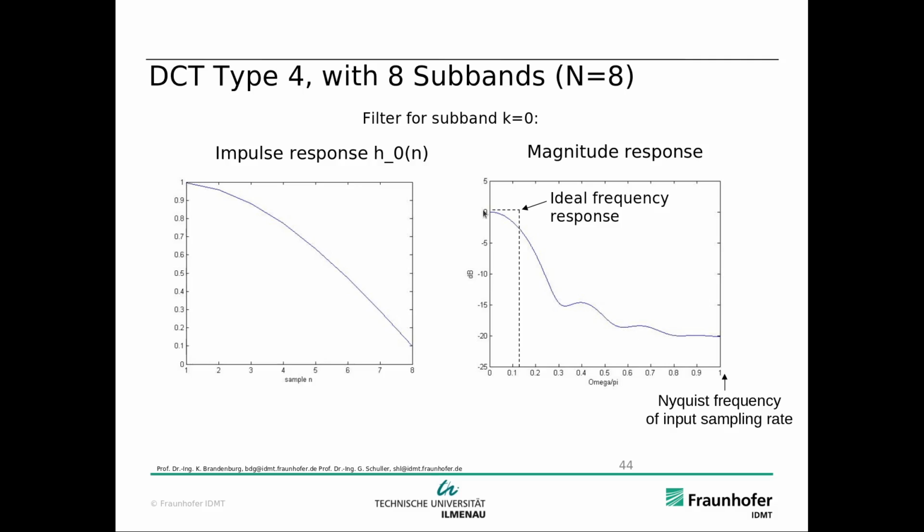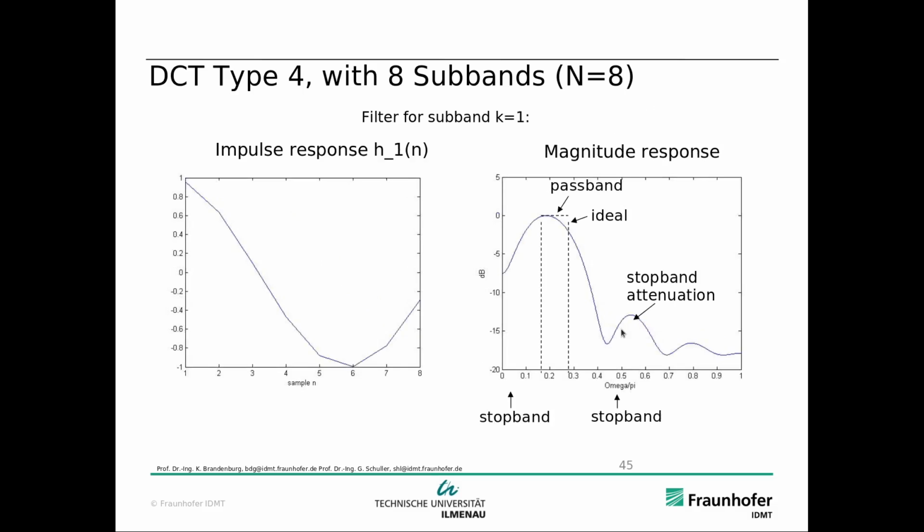And we can see the passband is not good and the stopband is even worse, right? We only get about 20 dB attenuation here at best. Here's the impulse response, which shows you it's fairly short, just 8 samples. So this is not really good enough because the ear can clearly hear what's attenuated by this filter. Yeah, so this is a bad filter.